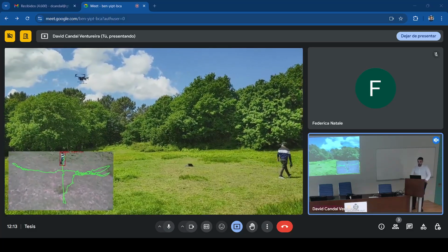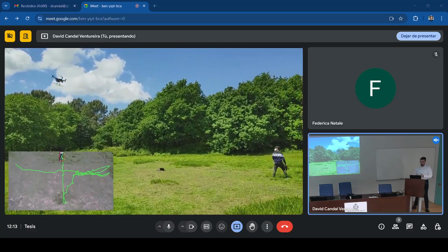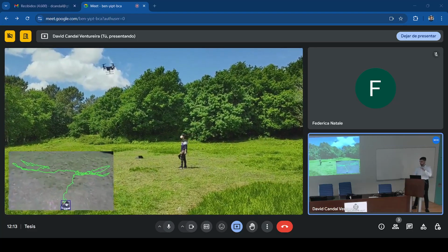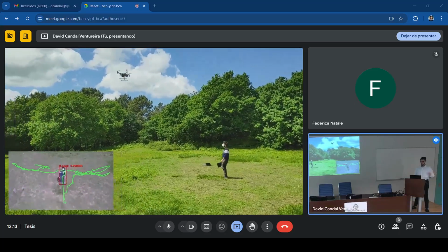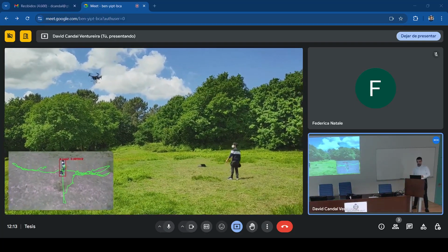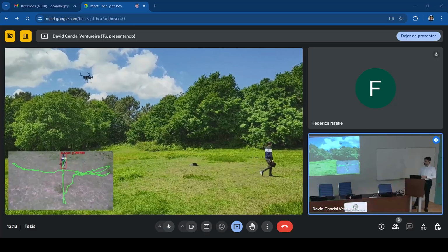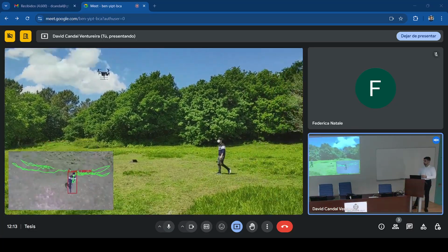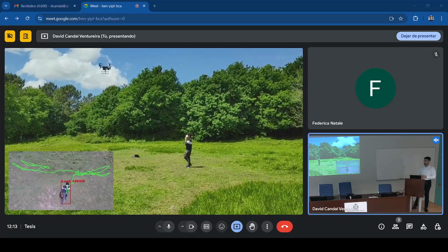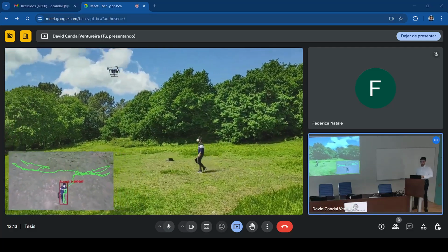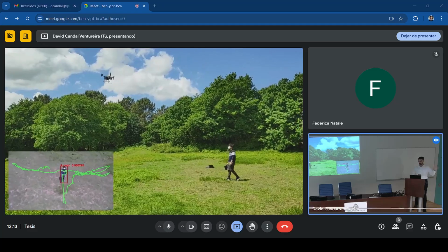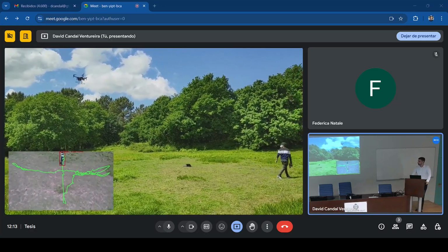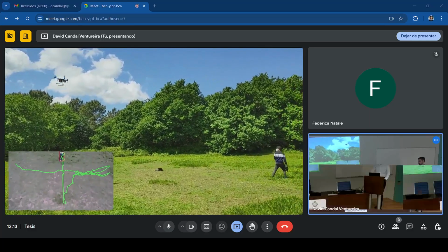In offloading, we split the application in 2 parts. Basically, we started the complex parts, those related to the detection of the person, and we ran them in an external computing server. And the application in the drone, which was run in a Raspberry Pi embedded in the drone, captured images using a web camera also embedded in the drone, and streamed these images to the server, which replied with a command to move the drone, which was sent from the Raspberry Pi to the drone through serial port.